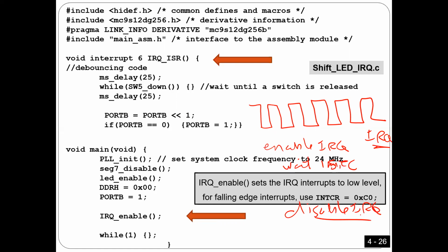Okay, so I'm going to enable IRQ only for 1 second. Why? Because I want to count how many falling edges we have. So this is one falling edge, one falling edge, one falling edge, one falling edge, and every falling edge means one cycle. You got what I'm saying? And then my count is the frequency.